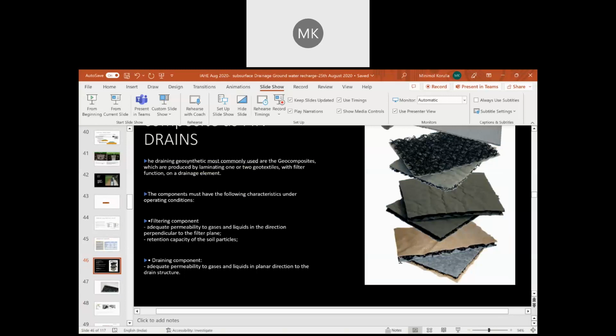You can try it, it is a very small equation, and using that we define the sand blanket or the capillary cutoff layer, which will act as a horizontal drainage layer, disrupting the vertical capillary rise.